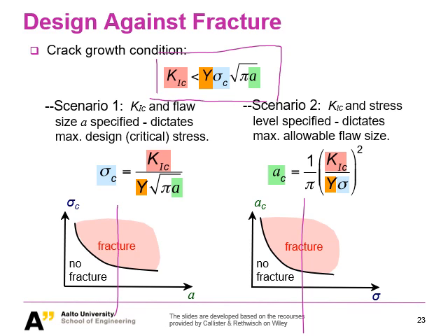That's why in many cases for our product, before they go into daily life, they're always detected with the ultrasonic machine, right? Now you know what they're detecting. They're detecting the largest flaw size. They need to make sure the largest crack flaw size in the material is not bigger than a critical value.